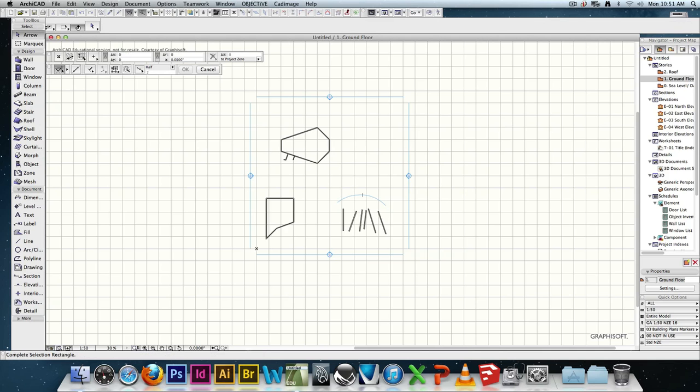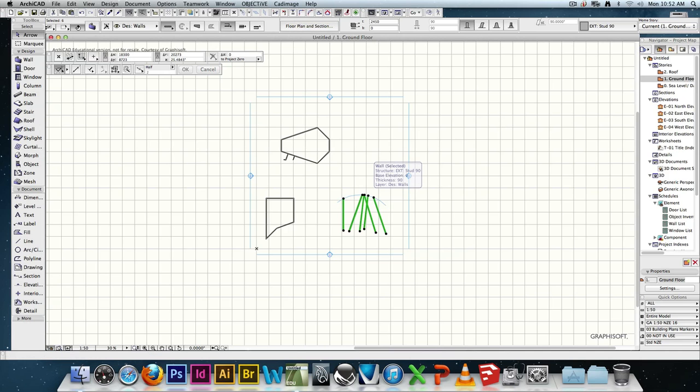So I can select all of these walls, and then, see this little guy up here? It looks like a whole bunch of walls in a line. And it says adjust if you hover over it. So if you click on that, and then you click on this line, ching. What I'm saying is adjust all of these walls to touch this line. And as you've just seen, it doesn't have to be a straight line. It could be a curving line.